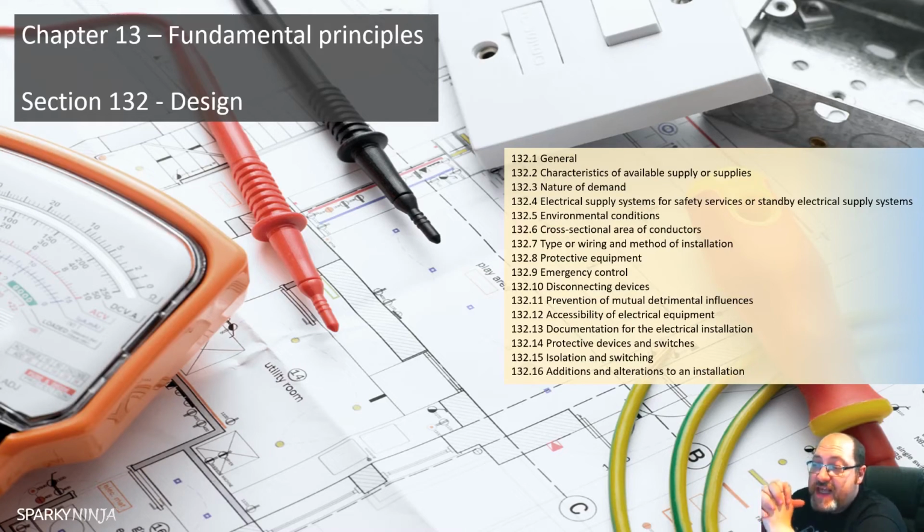For safety service and standby supplies, then we'll have to consider the characteristics of the supply and the circuits that are to be supplied by the safety source. So we'll have to consider segregation and compartmentalization. We'll cover that later on in the safety services section.